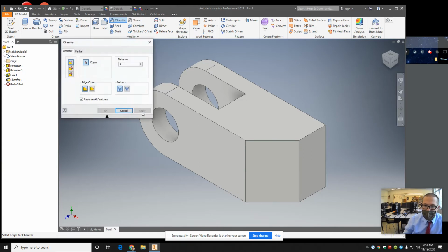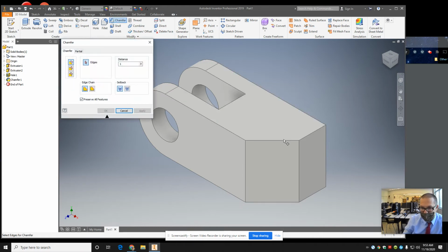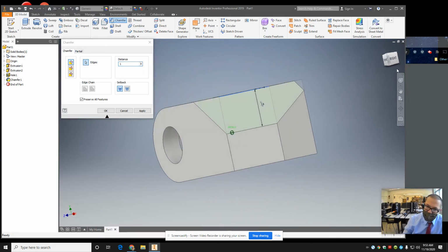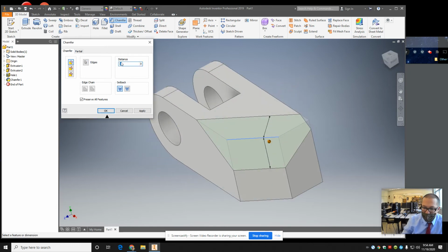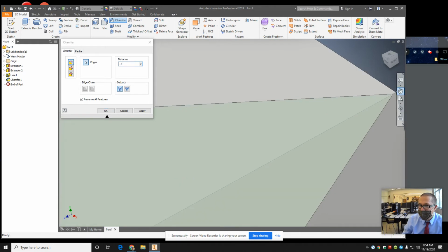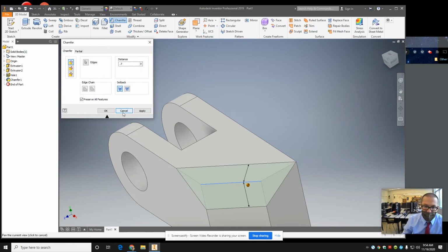Cool. Now, there's always a temptation when you get to this part to try to chamfer this edge, right? But look, it doesn't end up right. Kids always try to adjust this chamfer, right? The problem is they just try to kind of wing it and be like, okay, make it 0.8. Let's see how close we can get. Okay, that's 0.7. Oh, look, that looks really good, Harmon. I got it, right? But it's not. You zoom in, look, you got to be careful. It's not perfect, and the angle's not right. So there's a different way to do this.